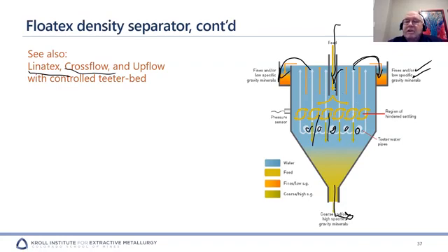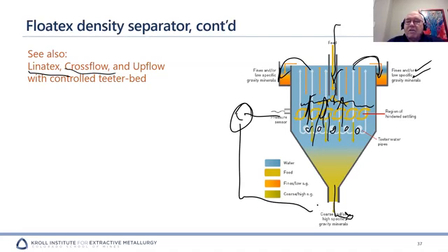Material comes in and starts settling. It encounters this water going in this direction, and there's a teeter bed that sits here with size material that just kind of doesn't know where to go, and it sits there, almost like a filter in the way that it works. It teeters, so it's called a teeter bed, and it's pretty well controlled because you have a pressure sensor here, and that pressure sensor works a valve down here that opens and closes the bottom, as you have a constant feed of water coming in, which causes this upflow action.